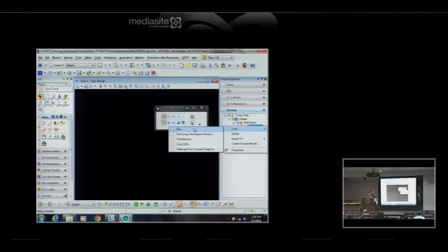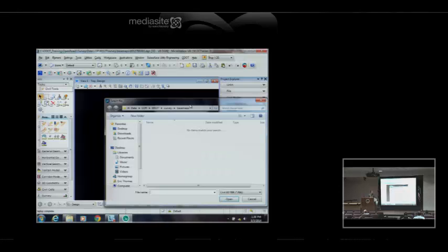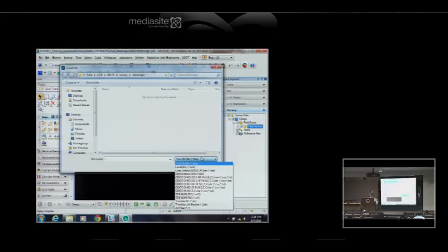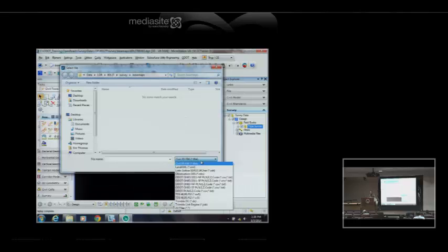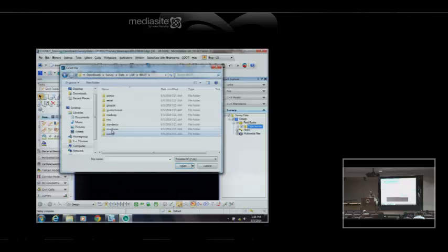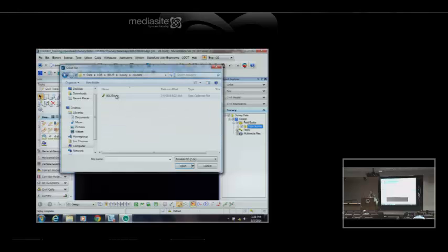So I've got a field book, and what I want to do is load a file into the field book. And I mentioned support of different formats. So there's some of the formats that are supported there. This list has been filtered to show the formats that ODOT uses, so there are more formats available than what's shown. In your survey settings, you can configure that. I'm going to bring in this first one, a Trimble DC file. It's under my survey raw data folder. Go ahead and bring that in.